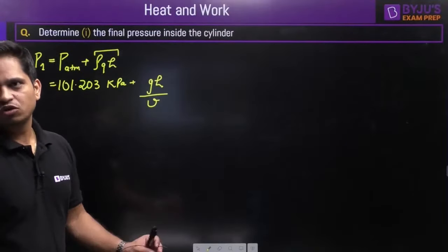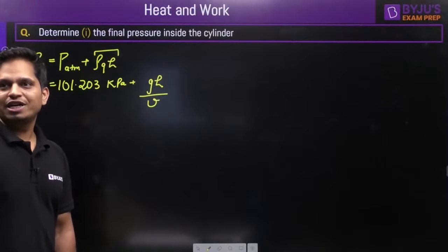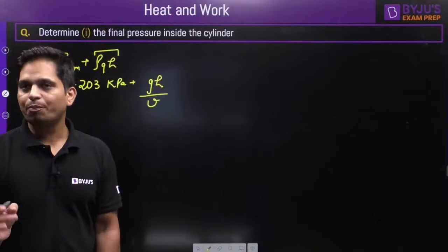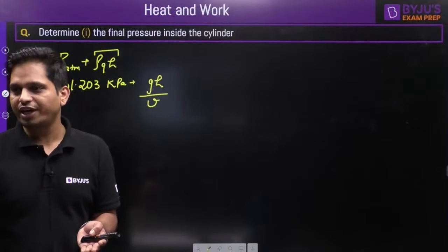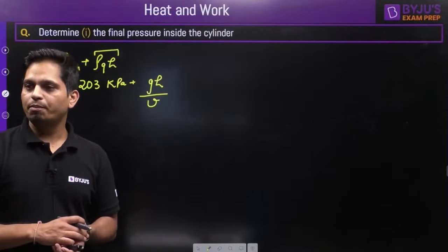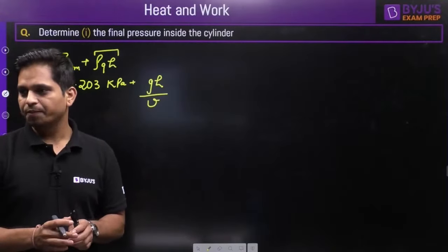143.23. No, that is not correct, I think. It's given adiabatic, so why are we considering it? No, they are saying the piston is adiabatic. Piston cannot transfer heat. There is no heat transfer that is going to happen from the piston. Piston is adiabatic. Heat transfer process is not adiabatic.